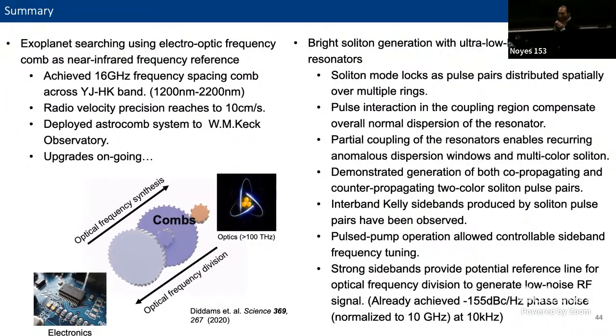Just get the third harmonic of the whole thing. I believe that is possible, because we have third order nonlinearity in the silicon nitride, and that depends on what you are thinking about. If you are thinking about getting a third harmonic of the full comb down to the 3F region, that's going to be hard, because it's hard to get phase matching conditions to do this 3F generation in the resonator for the full bandwidth. That's going to be hard. But if you think about generating a 3F first in the silicon nitride and then generating